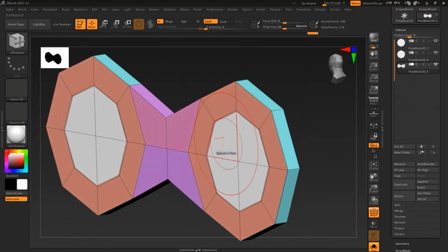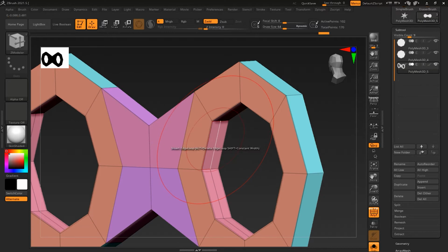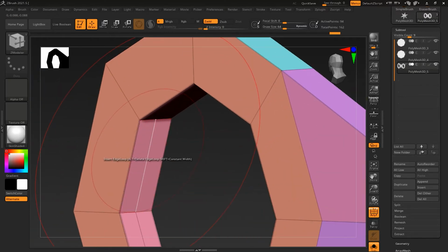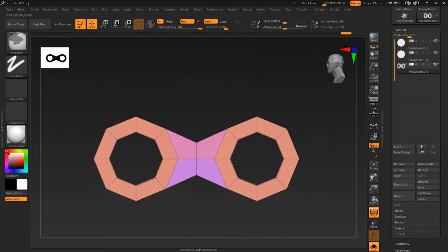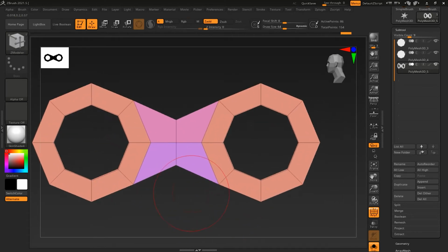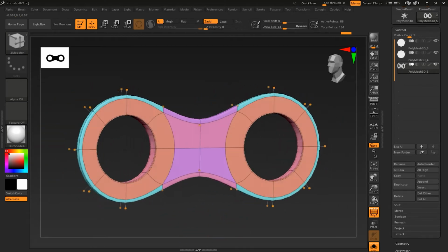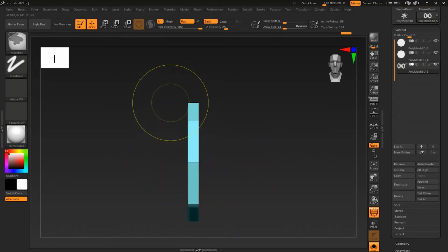Choose single poly and push it down to the other side to delete that. Hover over the edge again, delete that. So why do we delete? Because you should try to keep it as low as possible, because this is going to be worked as an IMM and it's going to be a lot of tools, so it's going to be messy later on. It turns out I think we deleted the edge accidentally.